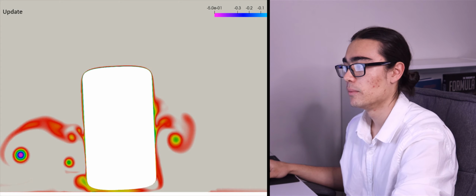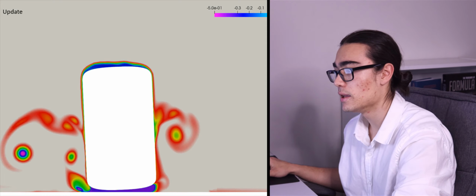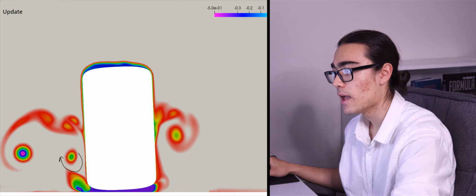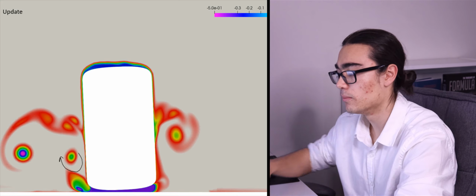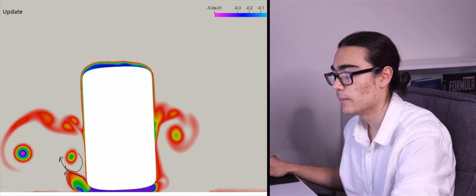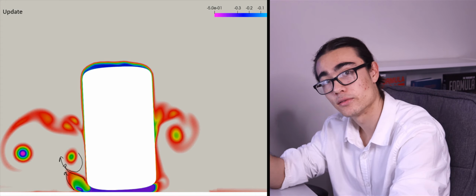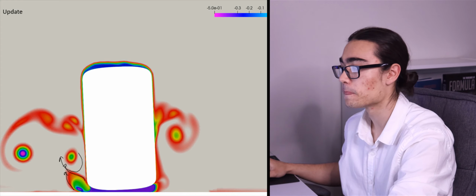Okay, a bit further back, base and update. Similar again, now our updated case has kicked up a little bit more squirt this time, but it is being drawn in between these two systems here, so in between the Y250 and the straight vortex. You can already see the way that it's passing in like this. So for a more optimized geometry, if you were to give this a second iteration, you'd definitely try to look at moving this straight vortex perhaps a little bit lower.